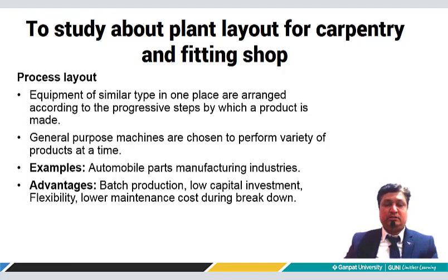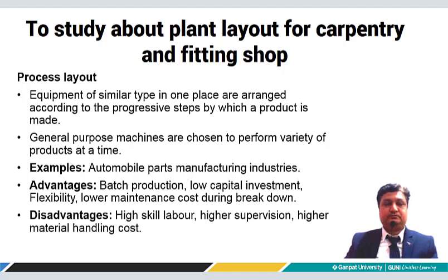The main advantage of this type of layout is that we can perform operations in batch production. It consumes low capital investment and it allows flexibility and lower maintenance costs during breakdown. But the disadvantages are that it needs higher skilled labor, higher supervision, and higher material handling cost.